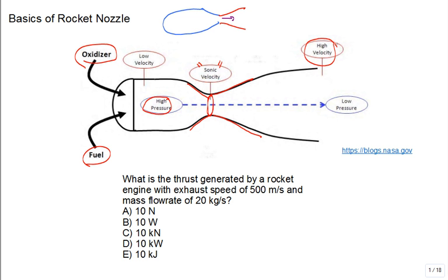You can get the speed of the chunks of gas coming out here faster than the speed of sound in that gas. This is incredible. This is mind-blowing. All right. And then the pressure will continue to drop, and at the exit you still have the lowest pressure. So the pressure in the throat will be higher than the exit pressure.